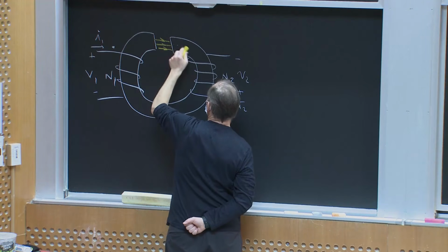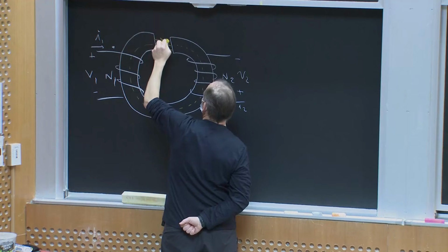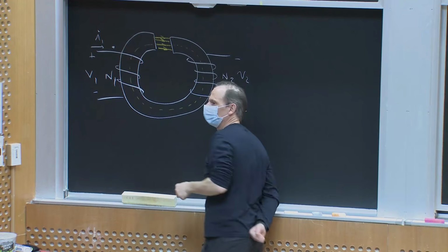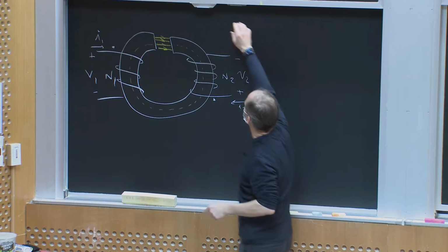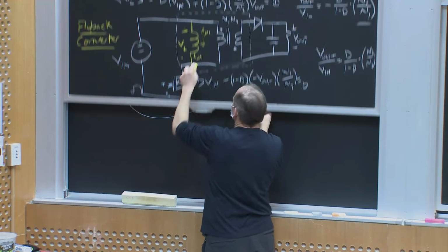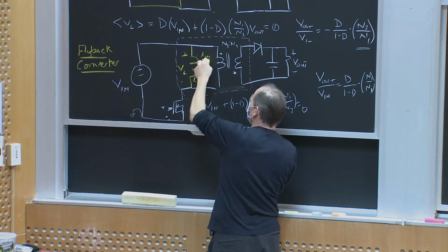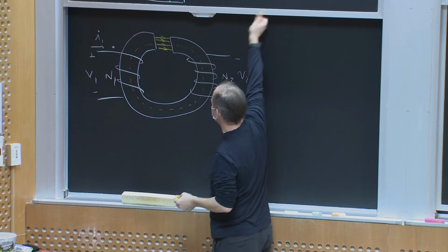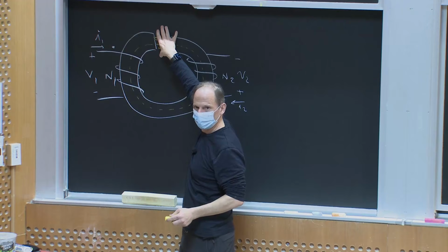So maybe there's a tiny bit in the core, and if this is H that I'm drawing, but most of my energy is stored here, okay? How is that reflected in this circuit diagram? It's reflected in the magnetizing current, right? 1/2 L mu1 I mu1 squared reflects the energy stored in the core and in this gap. Okay, mostly in the gap. Make sense to everybody?